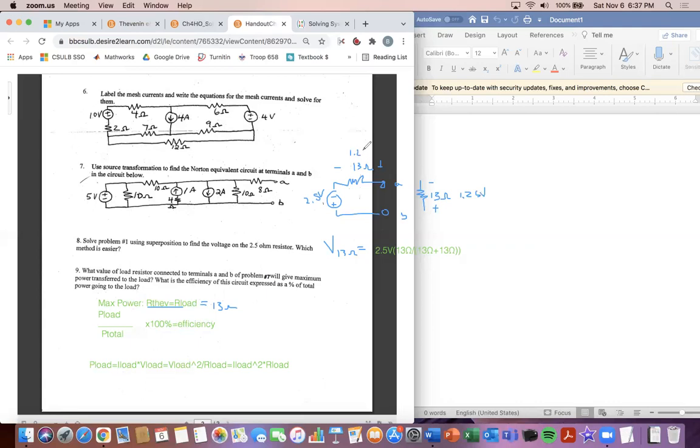And we can plug that now in to find the power across that load resistor here, this 13 ohm one. And so knowing V load, which is 1.25 volts, squared. Did you introduce that 13 ohm resistor as like a load resistor? Yeah, because remember here, RThev is equal to R load, and our RThevenin was 13 ohms. And so that's why I said our R load was 13 ohms here. So I just attached that to A and B. Okay, and then you just did regular voltage division. And I found how much voltage is going across that load resistor now here.